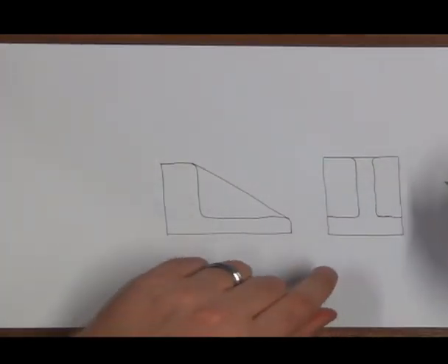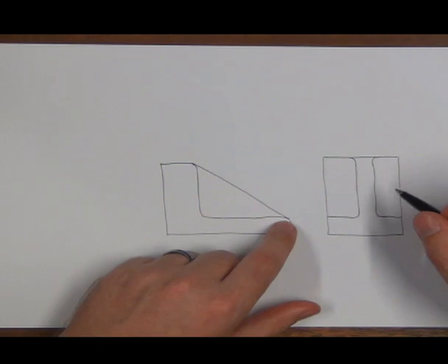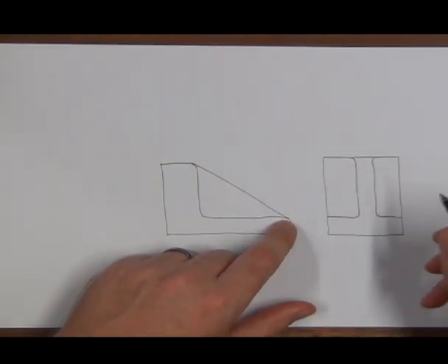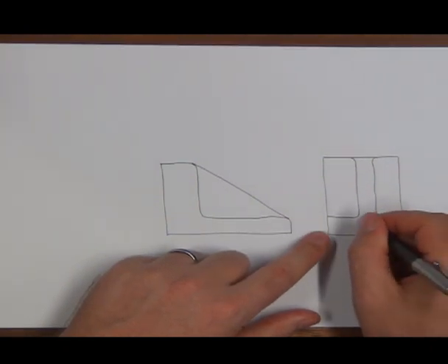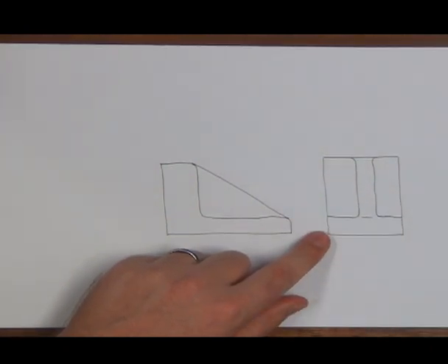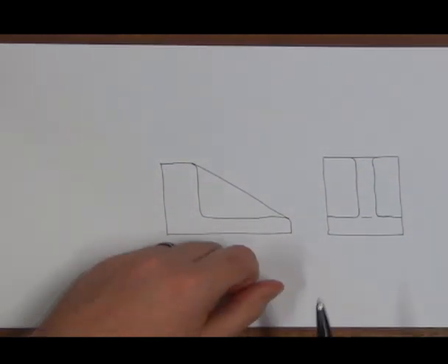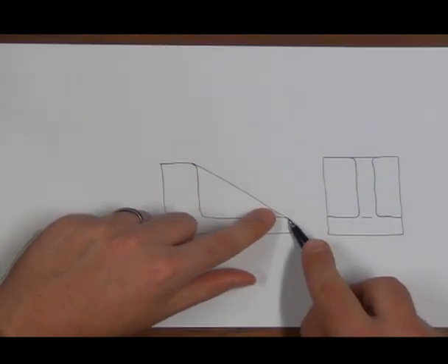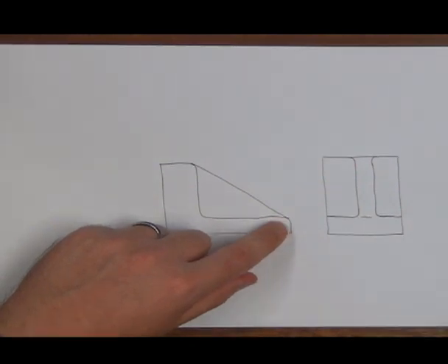So a standardized way to show that there is a change in plane, though not sharp, but also not very round, the standard way to do this then is to use your thin pencil and just make a thin line over there. That is the correct way to show a tangency from a flat plane on a small radius. We use this thin line over there.